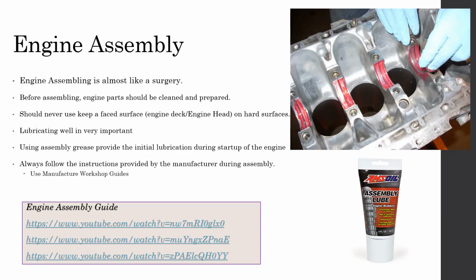One advantage of using this sort of lube is that it works with the engine oil. When the engine oil pressure is building up, the assembly grease will automatically dissolve in the engine oil itself without creating further damage. Using any other grease types is not recommended. You should always use assembly lubrication grease.